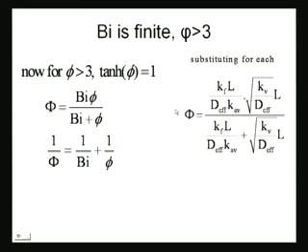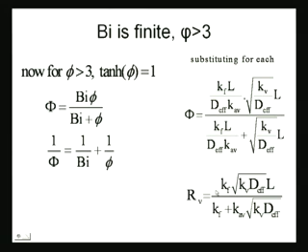So this is one limit that we are looking at, and to go a little quick today, because I am going to finish this a little bit. Fine. So now your Rv, that is your observed reaction rate, you can measure in terms of this, and this is the expression that you get. So if you want, you can write it down. This is proportional to Kf, the mass transfer coefficient, Kv, the partition coefficient, D effective, the diffusion, and length L.